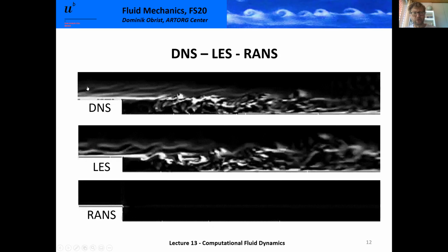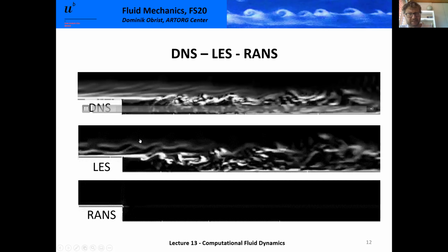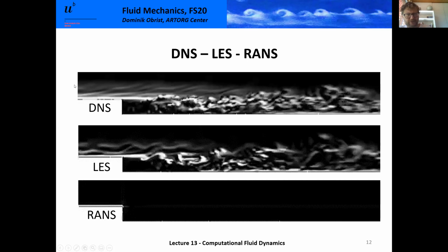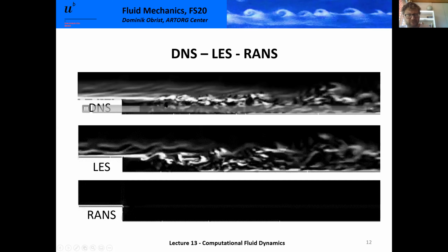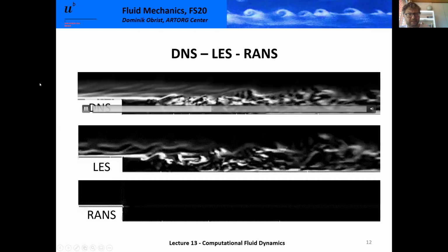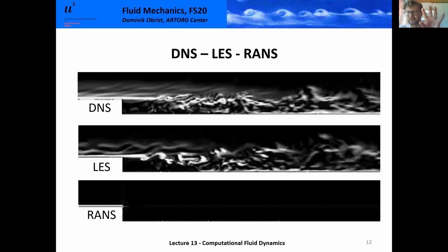So this is a flow over a so-called backward facing step. Flow comes in from the left and goes out to the right. And here you have this step which is going down. So you will get a flow separation here, and the flow becomes turbulent, and you get a reattachment here, and you get turbulent flow structures all around here. Let me show you what this looks like. See the flow coming in more or less laminar. About here, it breaks down, very turbulent, and you have the recirculation zone here. This is a fully resolved flow. It's a DNS. This is pure Navier-Stokes.